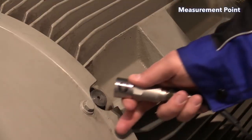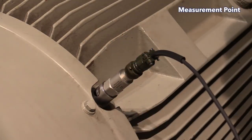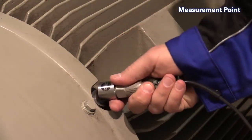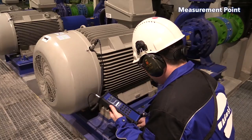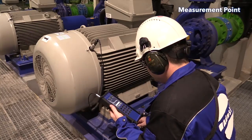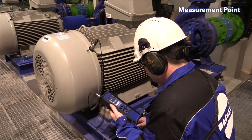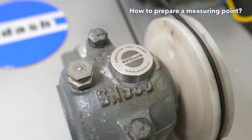The measurement point is the place on the machine, usually a bearing housing, where you place the vibration sensor and where you take your vibration measurement. The measurement point location must enable you to take repeatable measurements under the same conditions every time. Measurement repeatability is very important. How to prepare the measuring point?